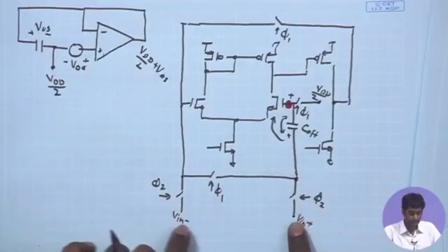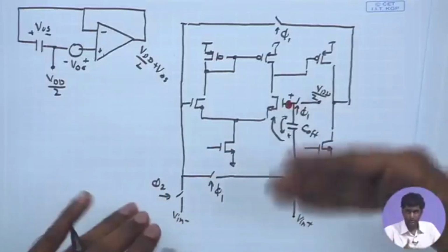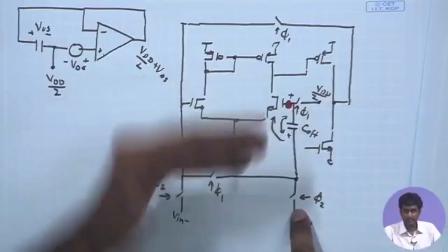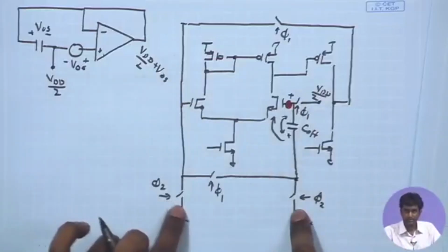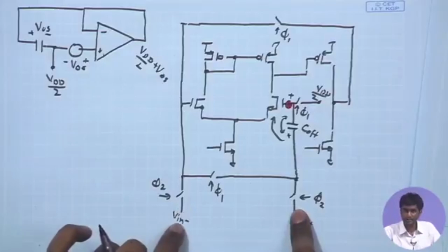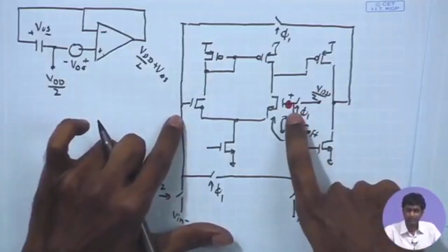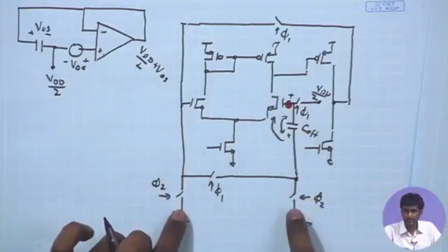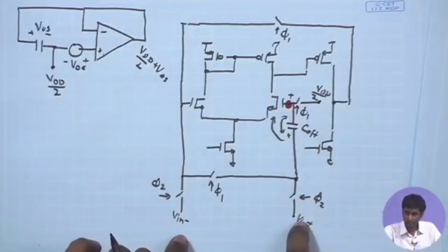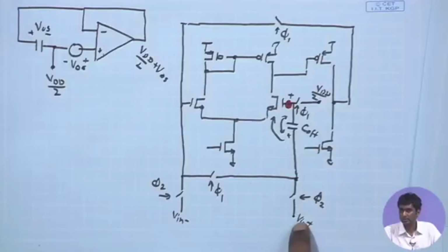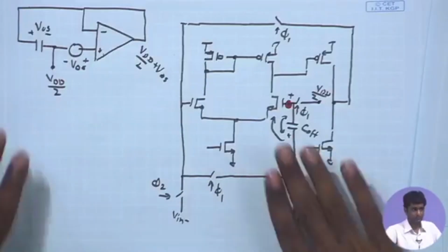So, as long as the input voltage V in is within the input common mode range of this comparator, we are just concerned with the trip point when the Vref approaches this sampled V in, and under that condition anyway the DC bias point will be provided by the sampled V in over here and the ramping voltage over here. This is clear? Any question?